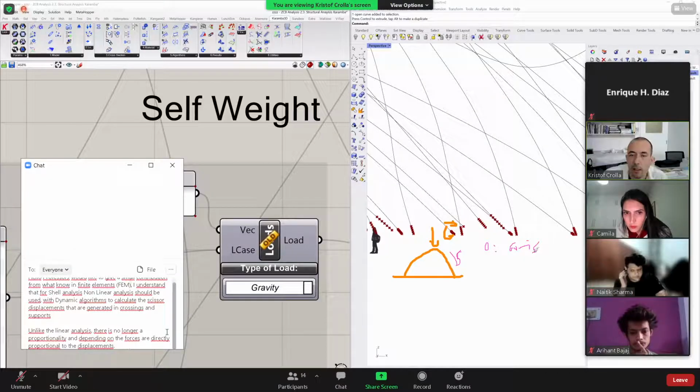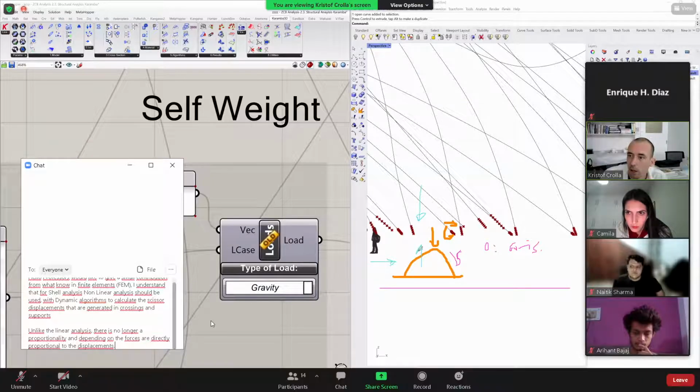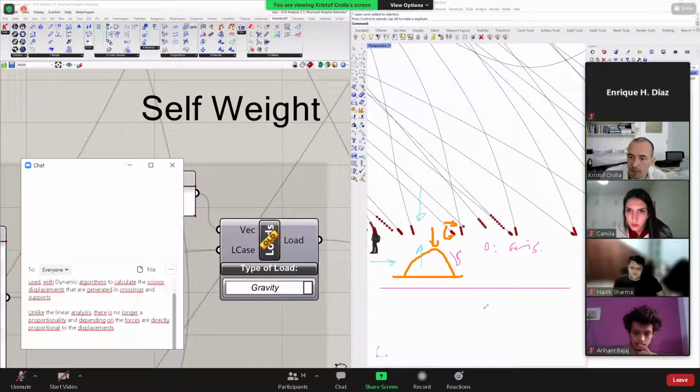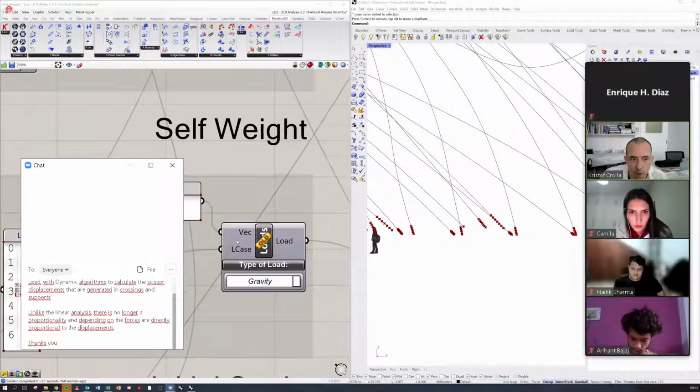Difficult to write here. And then there's a whole bunch of other load case scenarios that you can get, and that is if the wind comes from north, east, south or west, then if the wind comes from the top, which is a pressure, and then if the wind goes up, which is a suction. So there's basically 6 loading scenarios that we have there to consider as a whole. So the gravity works in all of the load case scenarios.